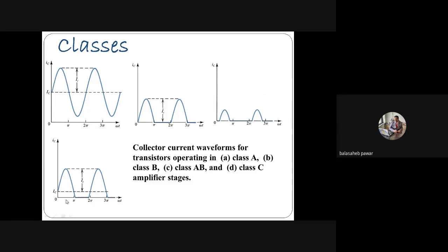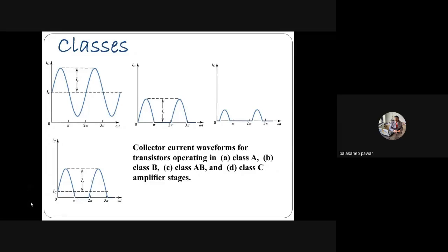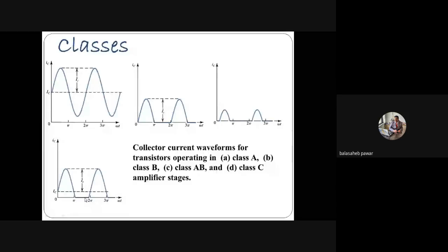You will observe the transistor conducts during the first positive half cycle completely, we can say. Similarly, partially during the negative half. Right? Can you observe it properly on your mobile? See, yes, the conduction angle of the transistor is somewhat greater than 180 degrees, but less than 360. It indicates what? The conduction angle is greater than 180 and less than 360, and that's why we classified it as class AB. That is between class A and class B.